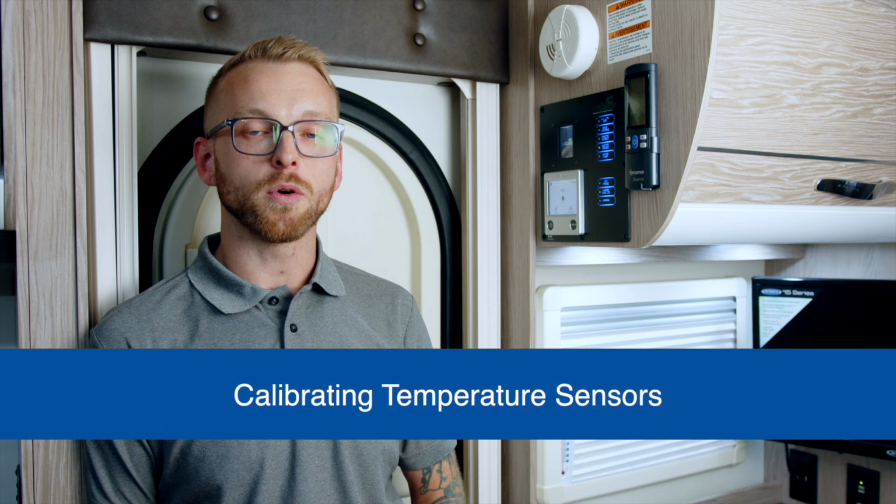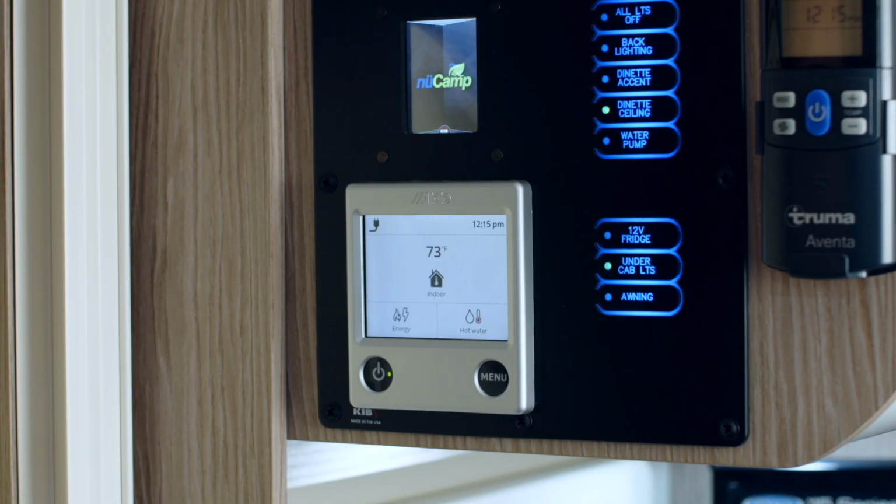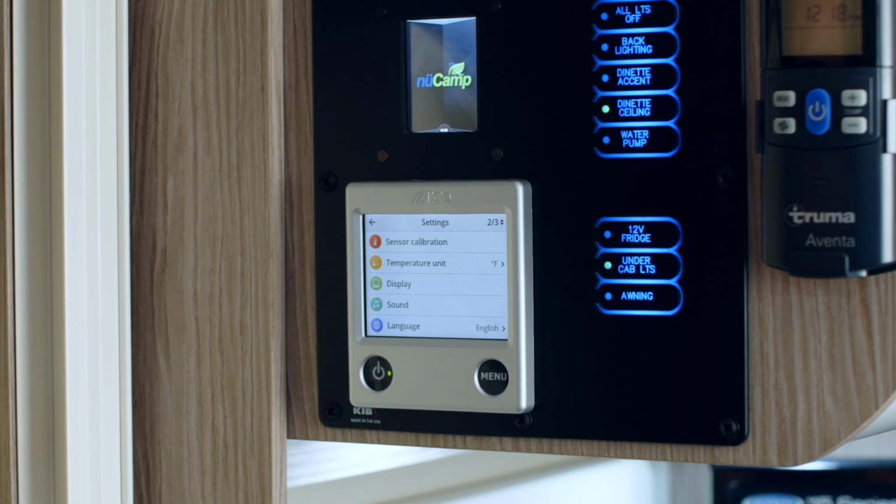If you do not wish to utilize night mode or day mode, simply turn off these options from the menu screen. The control panel will allow you to calibrate your temperature sensors for more accurate heating. If you notice the actual temperature inside your RV does not match the displayed temperature on the control panel, you may need to calibrate your temperature sensors. To calibrate your temperature sensors, select the menu button at the bottom right corner of the screen. We will then go to page 2 of the settings menu. Selecting sensor calibration will bring up the indoor and outdoor temperature sensor readings.